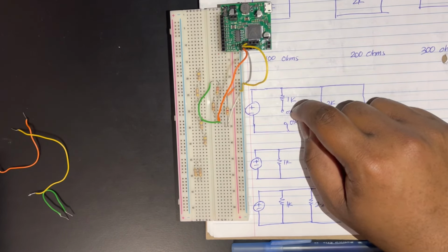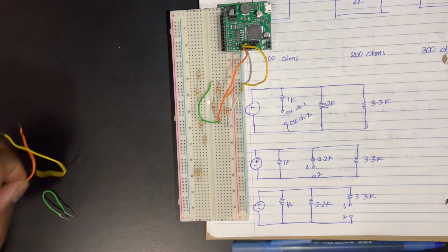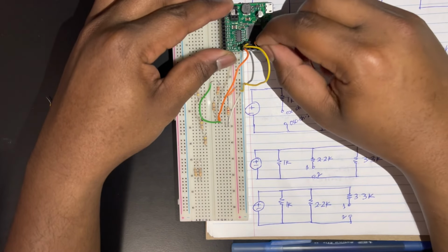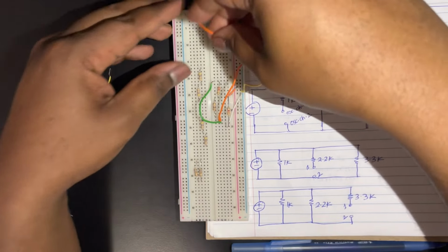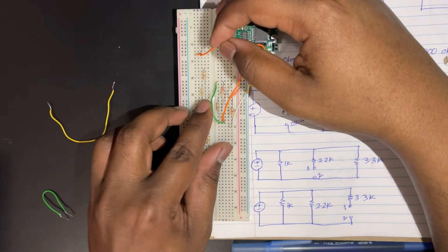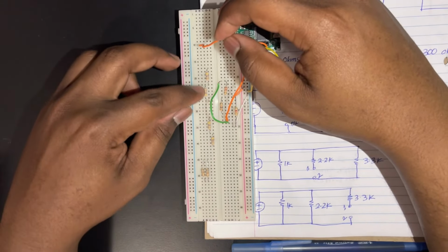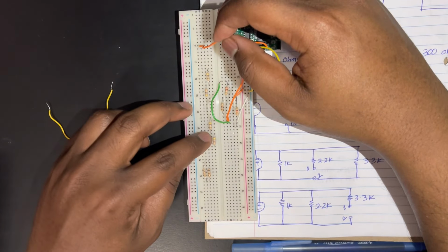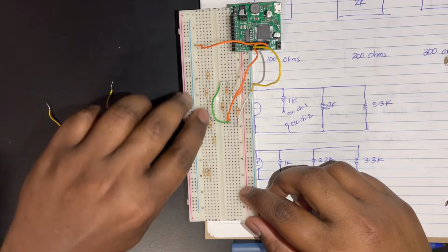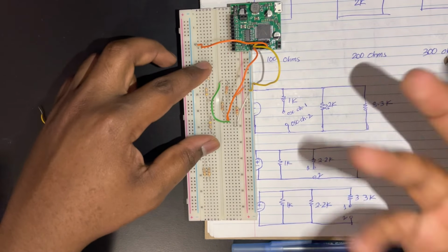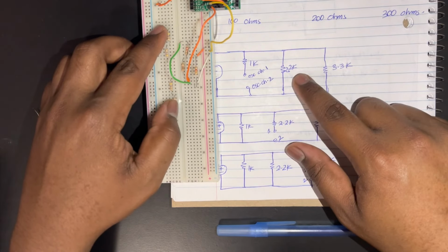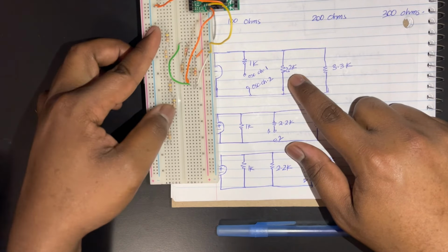What I'm going to do is take the duplicate channel of oscilloscope 1, and over here I made a 100 ohm connection, over here I made a 100 ohm connection. When I add all of this together, it would be around 200 ohm, which I would require for measuring the current when I'm trying to measure it through